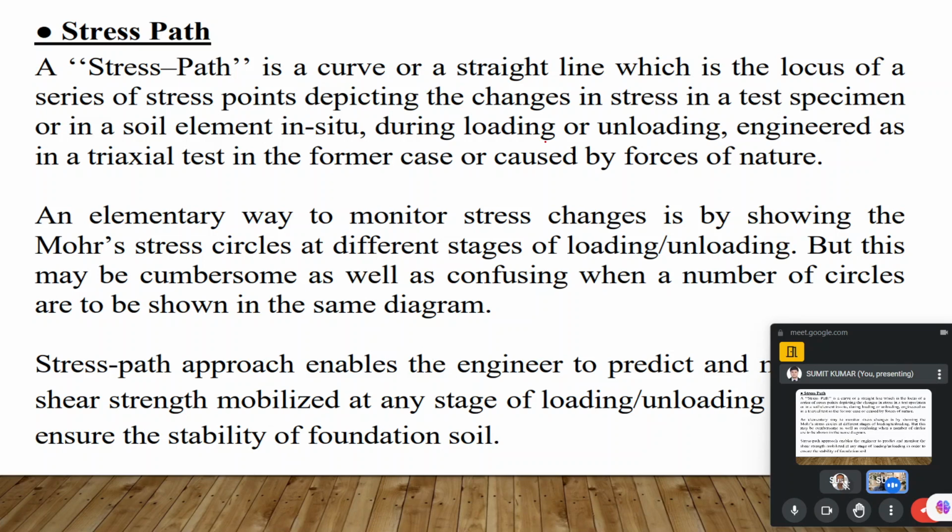An elementary way to monitor the stress changes is by showing the Mohr stress circle at the different stages of loading and unloading, but this may become crowded as well as confusing when a number of circles are shown in the same diagram.